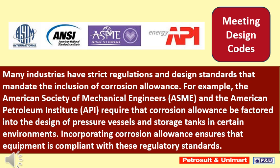Meeting design codes. Many industries have strict regulations and design standards that mandate the inclusion of corrosion allowance. For example, the American Society of Mechanical Engineers (ASME) and the American Petroleum Institute (API) require that corrosion allowance be factored into the design of pressure vessels and storage tanks in certain environments. Incorporating corrosion allowance ensures that equipment is compliant with these regulatory standards.